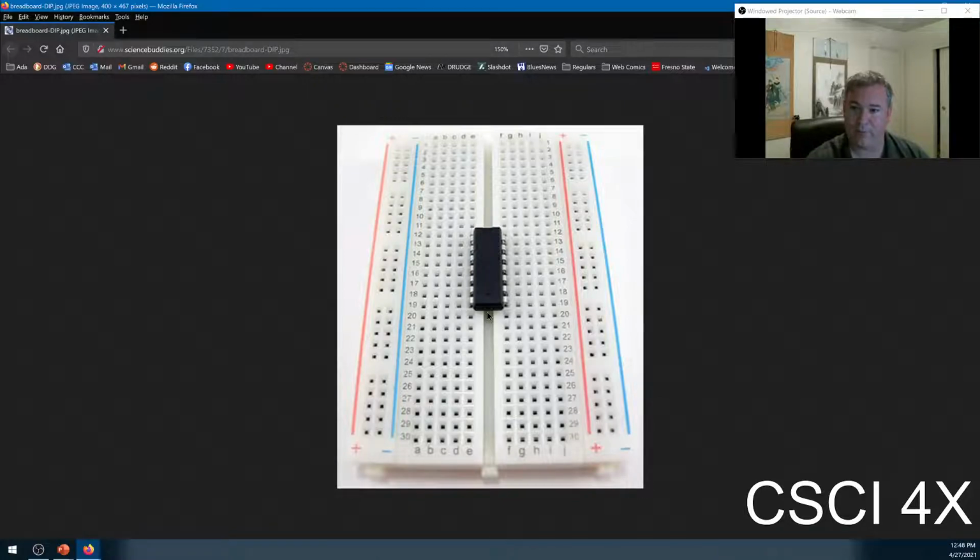And so what's nice about a breadboard is that you don't need to solder anything. You click things in and you can just rip them out, and when you put them in, they make a nice kind of connection. If you have a really cheap breadboard, it can get really annoying. You've got your wire and you're trying to put it in, and if the breadboard is misaligned, then the holes don't line up right, and you're trying to jam it in and work it. Really cheap breadboards, oftentimes the holes in the copper backplate don't line up with each other, and then you throw the breadboard away and buy a slightly more expensive one. Or you can work on it and try and make it work.